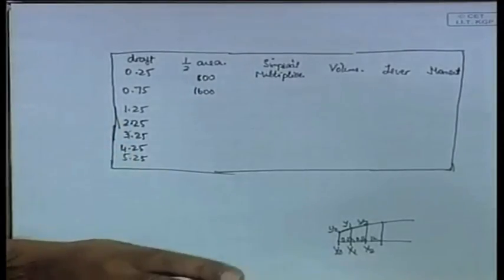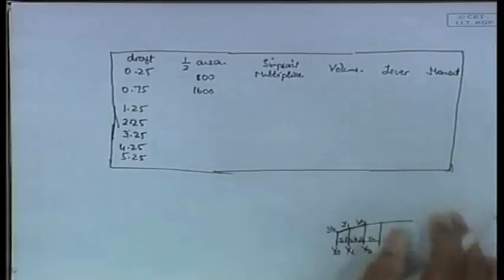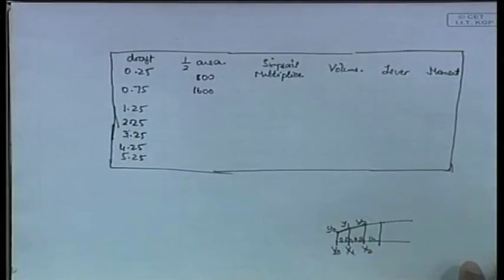To be honest, if I give a problem like this in the exam, it will take at least 45 minutes, maybe at least 35-40 minutes to do. But if you are able to completely do one problem like this, it shows that you have mastered the Simpson's multiplier rule, and also half areas, volume, moment, and I by del, all those things.